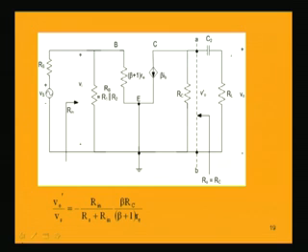Now, let us find out the lower cutoff frequency due to the coupling capacitor C2 and ignore the other two capacitances. The circuit of the amplifier having the coupling capacitor C2 only will look like this circuit, where the capacitor C2, which is at the output side, is basically coupling the output signal. So, the circuit has the other portion almost the same like the mid frequency region analysis.